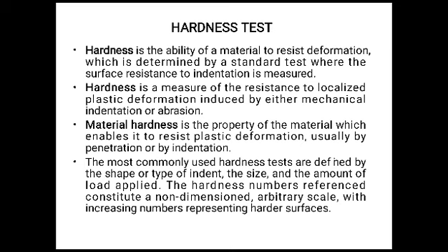Material hardness is a property of the material which enables it to resist plastic deformation, usually by penetration or by indentation. The most commonly used hardness tests are defined by the shape or type of indenter, the size, and the amount of load applied. The hardness numbers constitute a non-dimensional arbitrary scale, with an increasing number representing a harder surface.